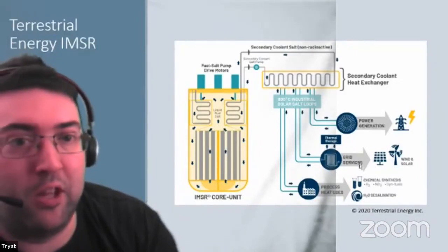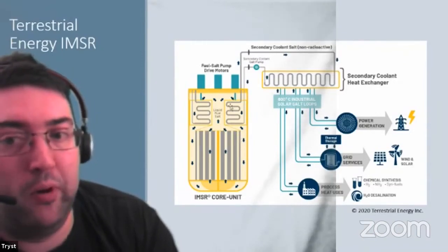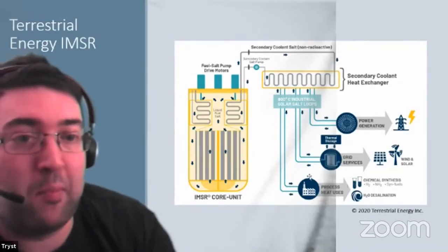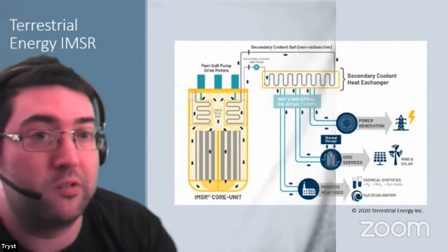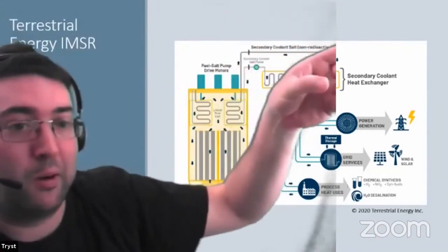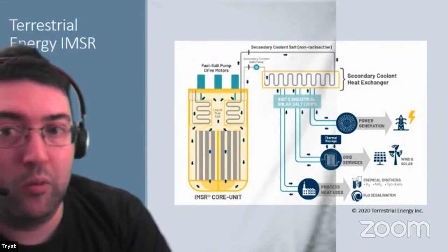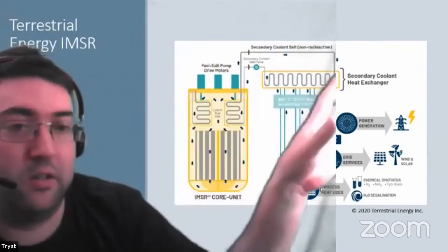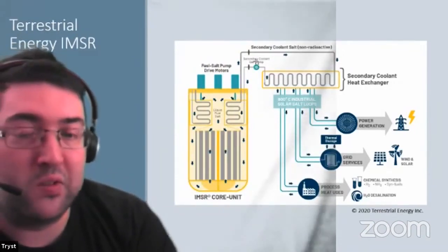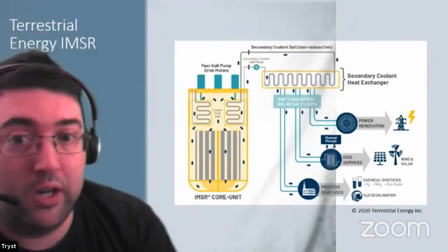So it's like making a big thermos of tea that you're going to enjoy later. So they can have a lower output from their reactor core, store hot salt in an insulated container, and then tap it later to make steam for power generation. So they're able to follow the load of the grid more closely with this reservoir of hot salt. And they also have the prospect of using heat from this to power other processes. But the main sort of beauty of this is the salt comes out at about 600 degrees, which is very efficient for power generation.